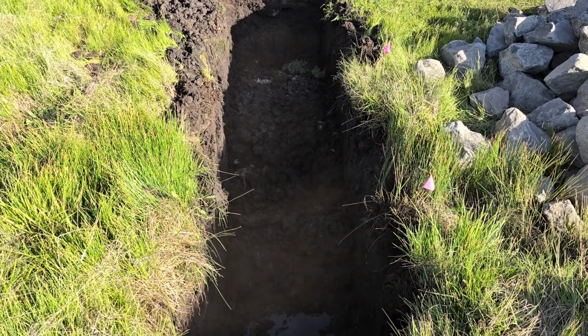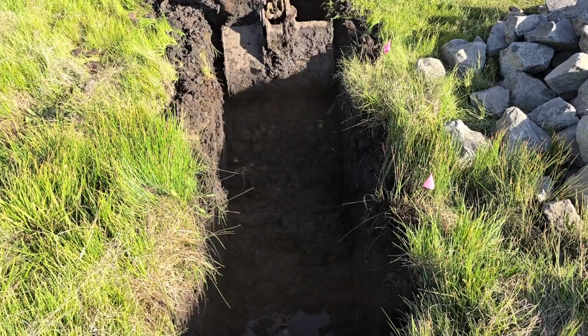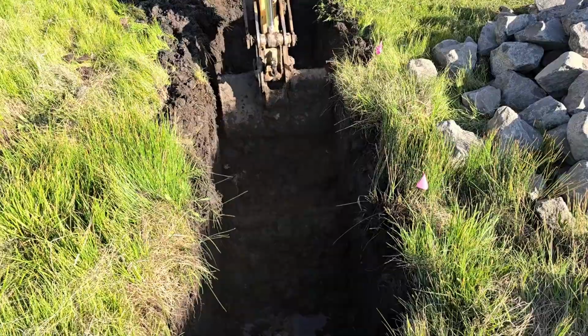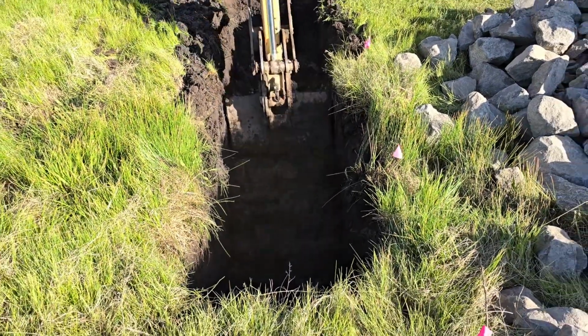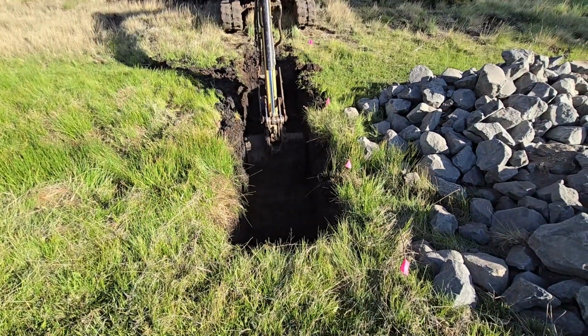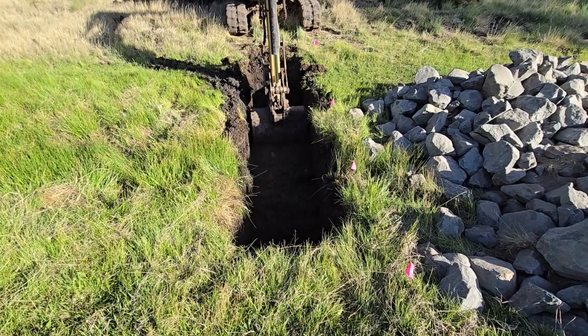This is a sign we have dug deep enough to cut through the permeable layers of soil that are carrying water below the compacted clay on the surface. If you wait too long to fill the core trench with soil, the trench will fill with water. Once it fills with water, it will not be possible to compact the clay that's placed in the core trench. This is because the soil will turn to mud and you can't compact mud.